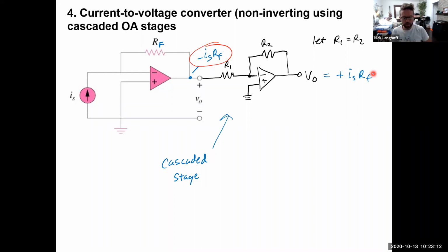The thing to do is use an inverting amplifier so that you can re-invert, or undo, the inversion that had been done by the current to voltage converter, with, in this case, a gain of 1. If all you want to do is just re-invert it, remember, for a gain of 1 you just let the feedback resistor in that amplifier equal the series resistor that's pulling from the source.